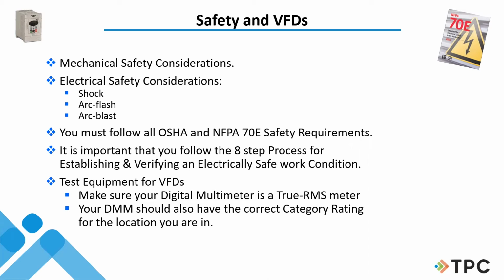So, make sure your meter's been calibrated and tested, whatever the manufacturer says, OSHA says. If they say every year, then you should get it checked and recalibrated every year. But make sure it's in good working condition. The leads and everything are good and don't have cuts and things in them. It's back to safety first.